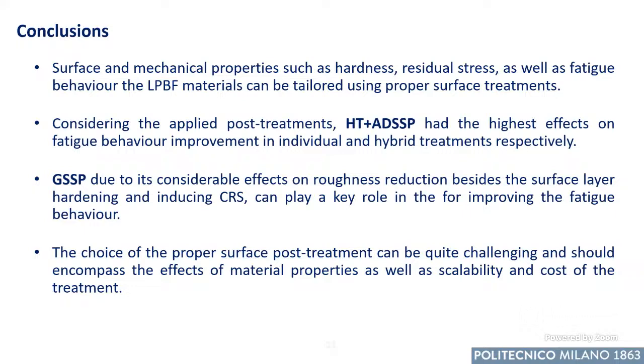is able to avoid the typical disadvantages, cons of shot peening related to the roughness of the material, and to avoid also overshot peening. And the gradient shot peening is effective to get the best result that are related to the different shot peening projects that are used so far.